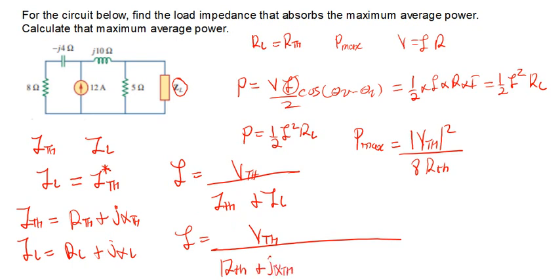By the way, this part here and this part are just simply talking about the reactance of the circuit that you have. So remember, initially I had said that for us to come up with maximum average power transfer, it's just a matter of matching the circuit and the load impedance.